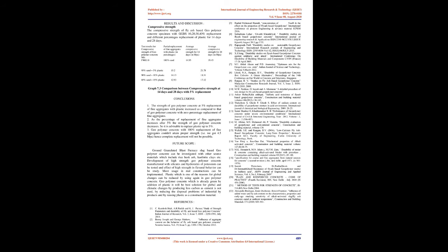Abdul Aleem and Arumairaj proposed an optimal mix for the alkali concrete. They reported that the alkali concrete presented high performance with reference to strength, and that high early strength was attained in the alkali concrete mix. The increase in proportion of fine aggregates and coarse aggregates increased the compressive strength up to the optimal level.